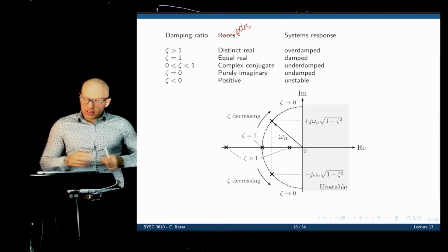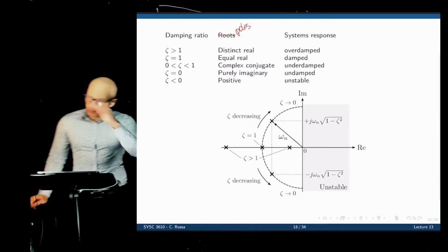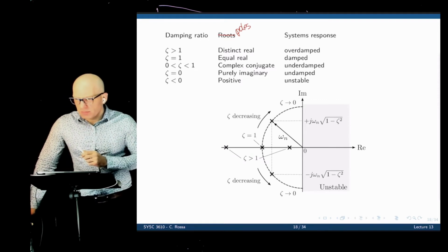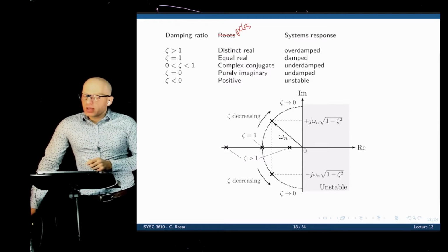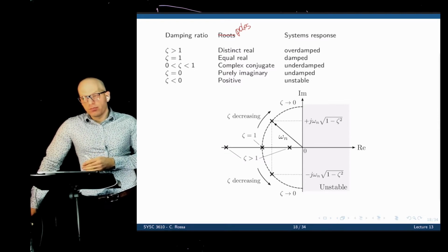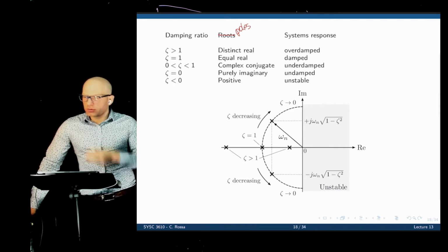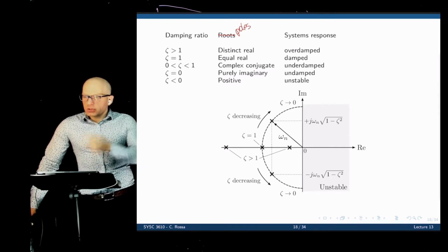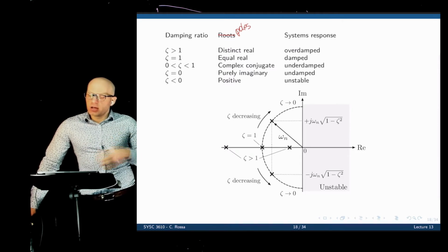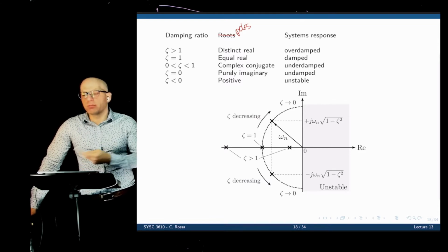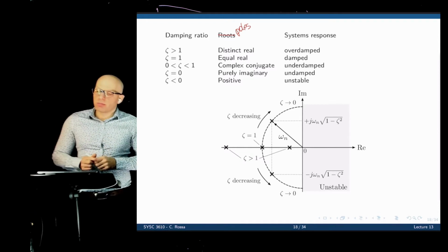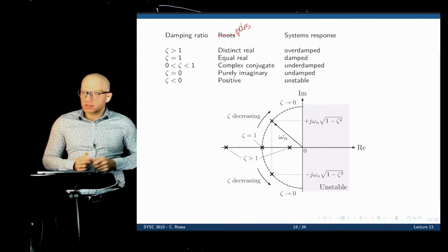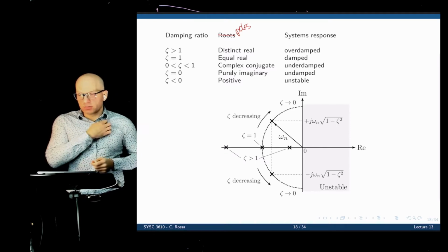And you notice now that in the control scheme we have, with a unit feedback loop and a control gain, we change zeta and omega n completely. So we can make a stable system unstable by controlling it too aggressively, or we can do the opposite. We can take a system that is naturally unstable and make it stable, such as a bike, for example. A bike is unstable without control, and we keep actively controlling it when we ride to keep it balanced. So it's an unstable system that with a controller becomes stable.